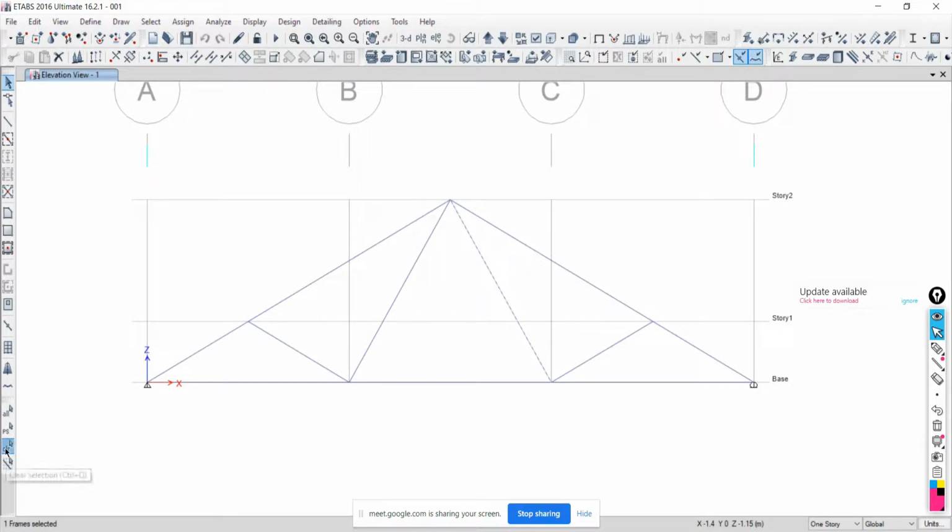If you are not getting it, try to understand: two criteria are there. When you are dragging from the right, first you click at any point, with the mouse pressed, and drag it. When this box cuts your element, that will be selected. In addition to that, whatever comes completely inside of this box will be selected. Two criteria are there. You have to drag, and whatever is cut by this box will be selected.